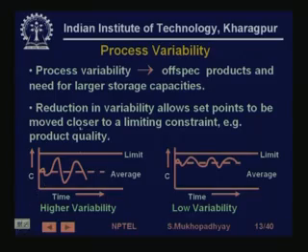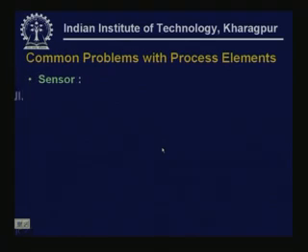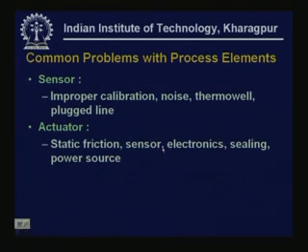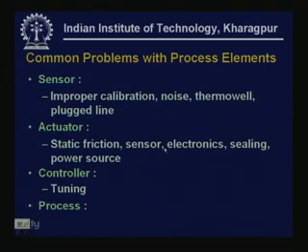So, you will try to play safe and you will actually set your limit higher. So, you will cut more material, then finally that additional material will have to be machined, and you are not only going to waste material again, but you are going to waste machine time. So, if you have high variability, generally you do not have good performance of processes.